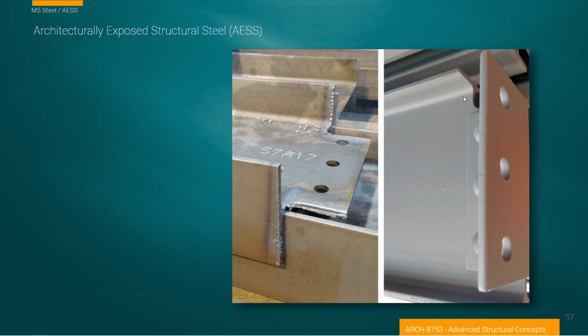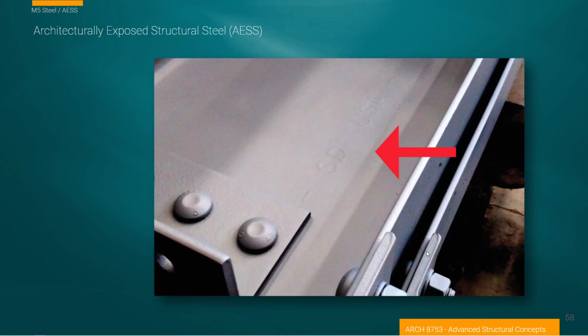And you can see the things that are actually removed. The weld spatter has been removed. The markings still exist. That would be probably commonly understood in our grading of this as an exposed piece of steel. You can also see pock marks in the face of that from the rolling operation of forming it. That's typically normal, and you'd probably be considered over the top to expect smoothness in that level of performance. So here again, I'm pointing out this grade symbol on the steel. It may be required, it may not be.